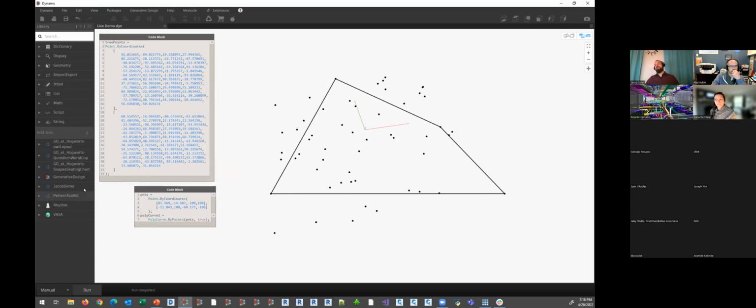So what we have to do is, under generative design, go into our data and put in a Remember node. Remember node is my favorite node in all of Dynamo because it means I can take anything, put it into this node, and run my graph. Right now it says null. Run my graph, and now I have a whole bunch of data. I'm going to do something crazy. I'm going to disconnect this, and then hit run again. That data is remembered. The content does not go away.